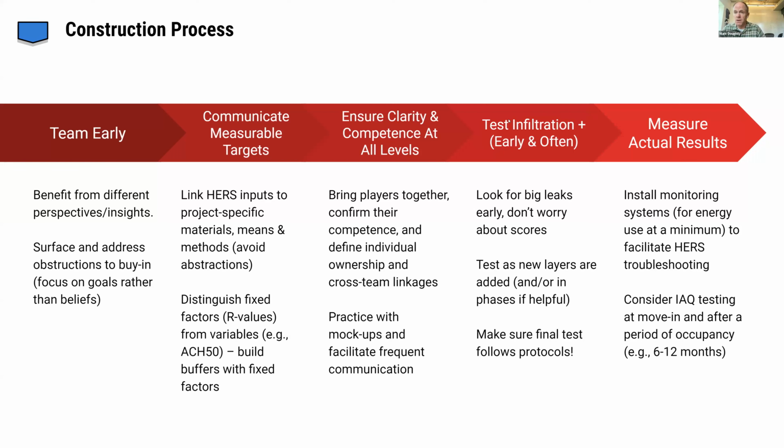Similarly, with some of the air sealing products we use, one of the issues we've run into is the compatibility between different products. So you have tapes and membranes, and if the tapes and membranes aren't compatible, they might stick on day one, but not long down the road, you're going to lose that seal. So this links to the idea of competence. Do people know how to do the proper taping and sealing? Clarity, do they know which materials to use?